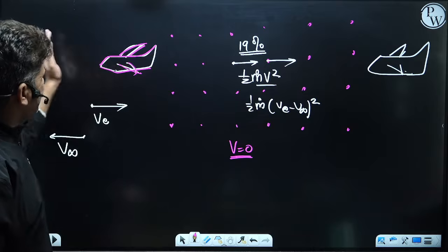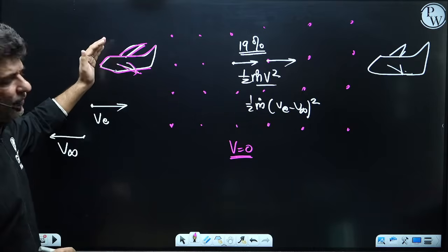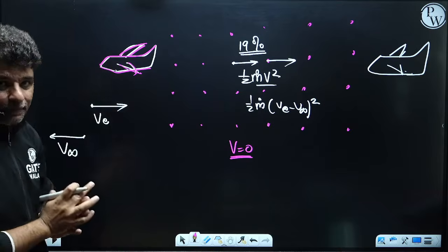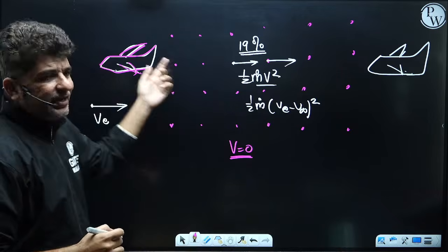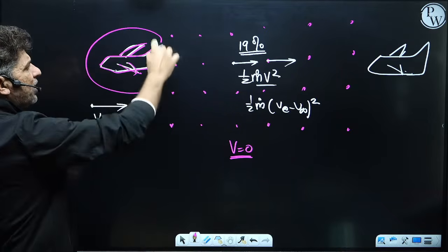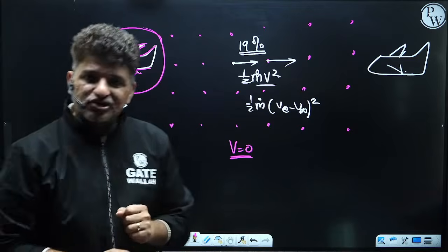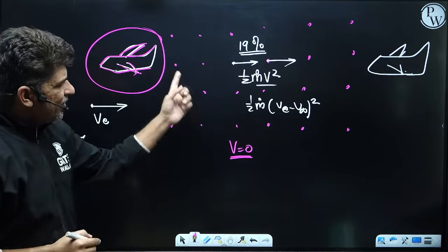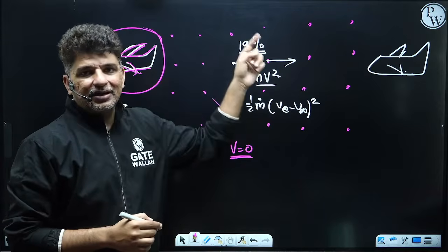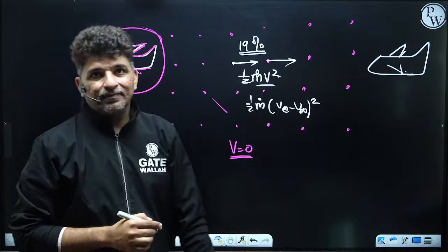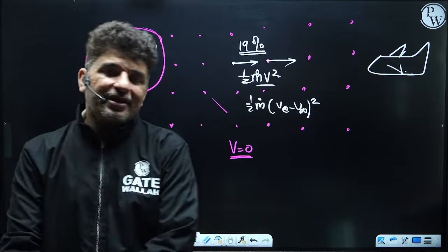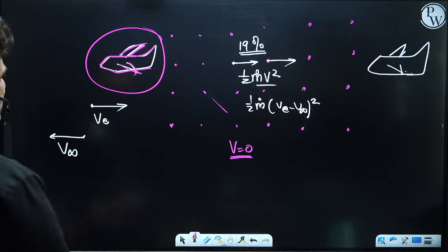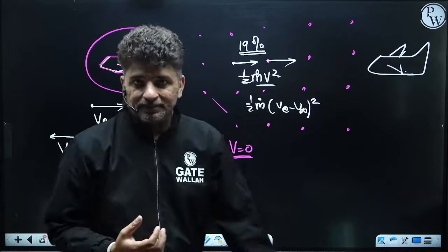There will be pressure drag from the nose of the aircraft, where certain compression happens. So 81% of the energy would be used to overcome the drag, friction, everything, and the remaining 19% energy is provided to these air particles in pushing backward. So now I hope everybody understands where the actual energy provided by fuel is going.